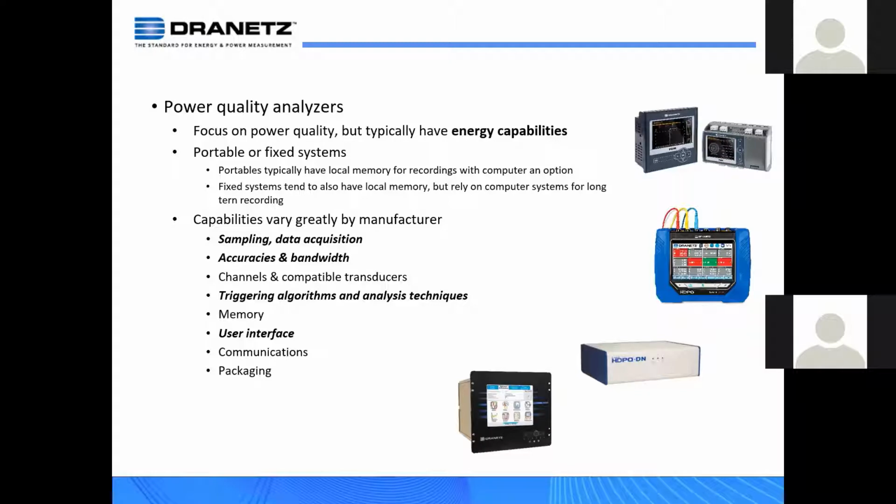A good standard to look for is IEC 61000-4-30, being Class A Edition 3. That's a topic, I believe, for our 3rd web meeting when we talk about power quality capabilities. That's a very, very important thing for a modern power quality meter, is to have those capabilities. All of these are compliant with that standard, which all but this meter over here from the 61000 supports the latest revision.